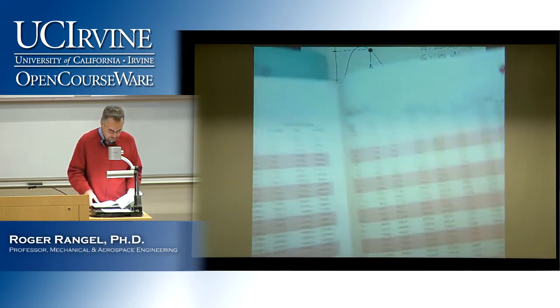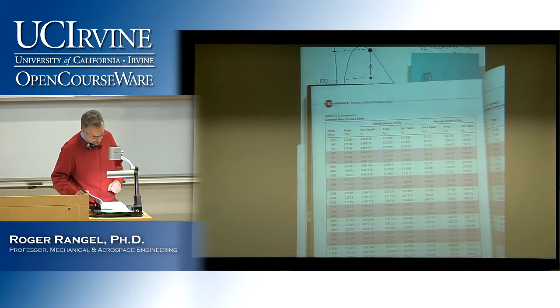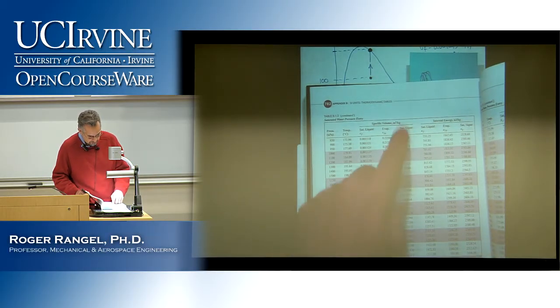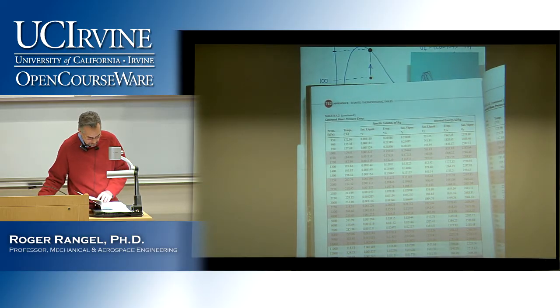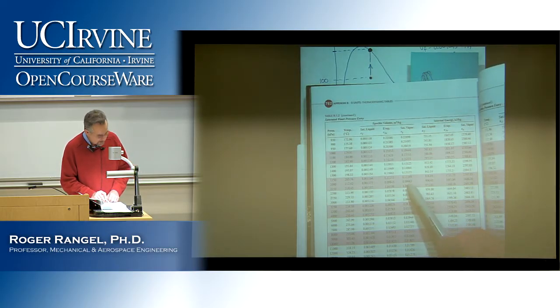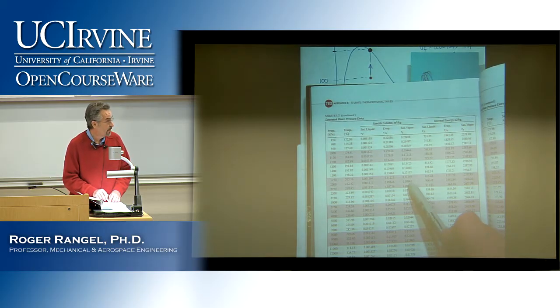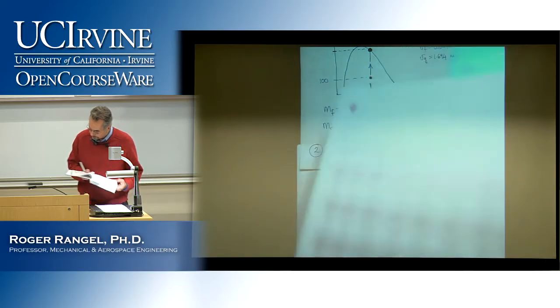800, so I've got to keep going to the next page, which starts at 850 kilopascals, and now the volume starts to get where we want it to be. So, for example, since we're just rounding things up, this is very, very close, 0.099. I'm going to take that to be 0.1 for vg, and you should too if you're working on an exam. So that's my 0.1, and therefore that's my pressure, 2,000 kilopascals. If I want the temperature, I can get that temperature too.